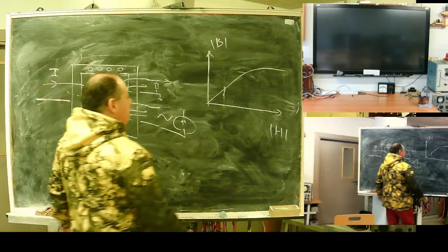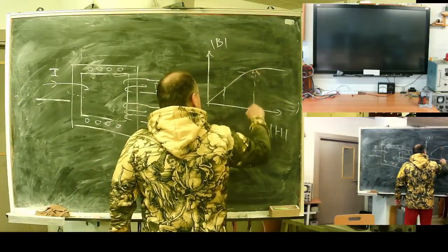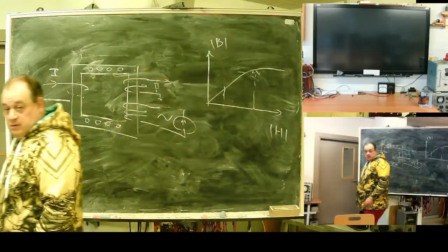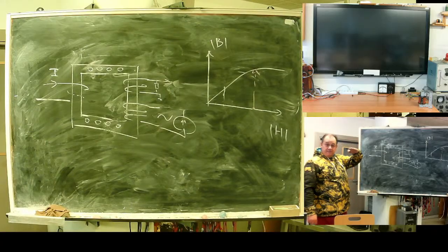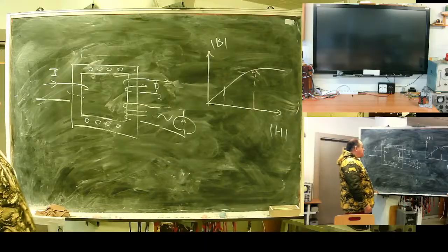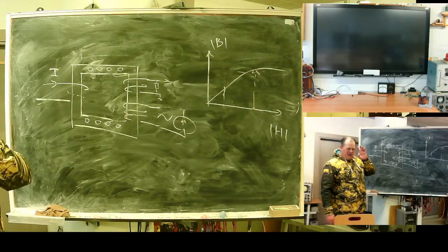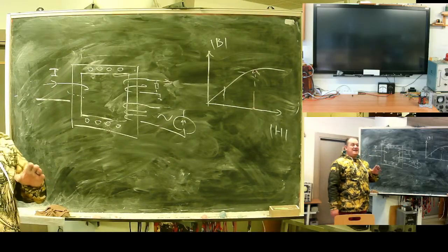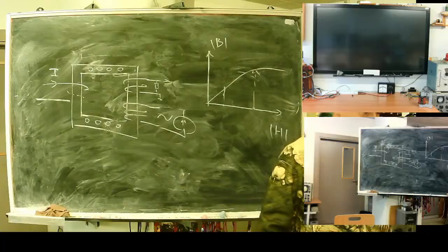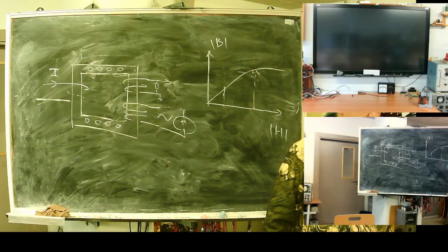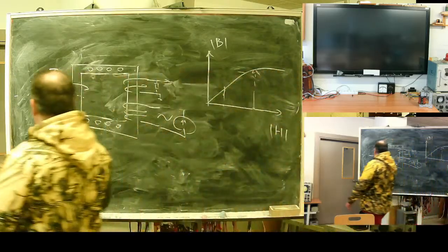With higher current, the working point shifts into saturation, and output decreases. With a specially crafted core, it will never be linear, but we can have a decrease, not an increase, but a decrease in proportion as a function of input DC current. This is DC.